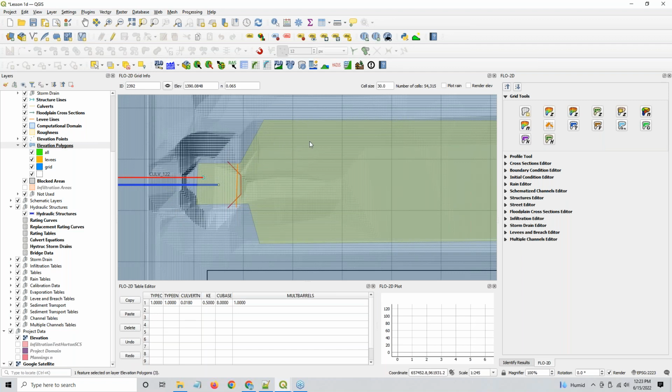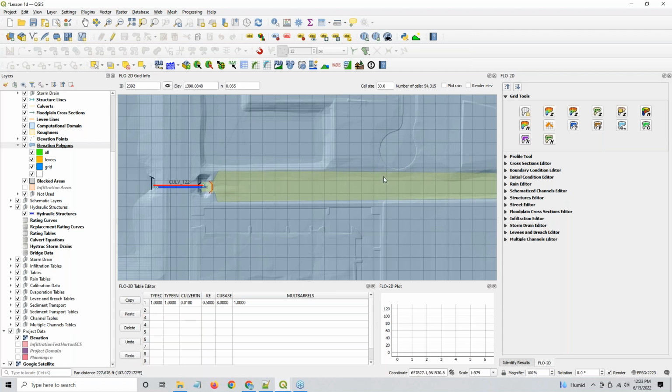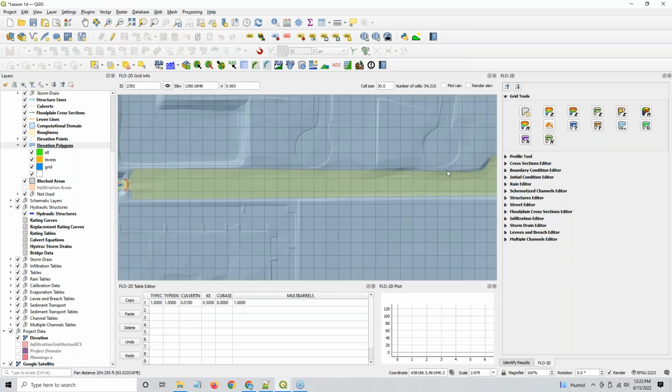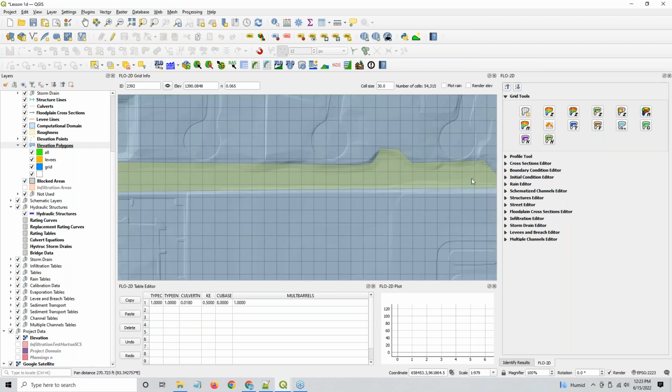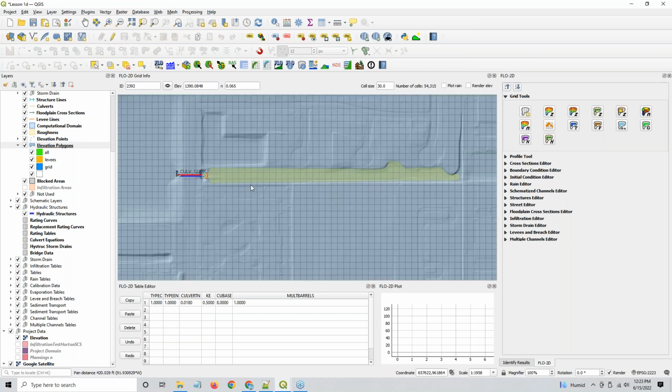And these ones all went down as well. They all went down to the minimum of those rasters. So it kind of gives you a control over your basin. Now this one was maybe a little bit overkill, because I probably gave this a little bit too much control, a little bit too much volume in that particular area. But you can see how that would be helpful, and how you could use that to help define your basins, or define little weird things like this that require a minimum elevation instead of an average elevation.